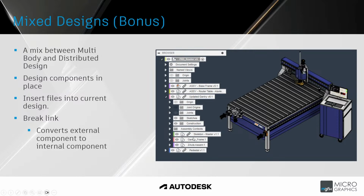One thing you can do is, let's say the updated gantry, we want to for some reason break the link to that external file. That is possible as well. This allows you to essentially insert a component. Let's say I'm going to use the pedestal actually as an example. It allows you to insert a pedestal. It might be a standard component that is used across multiple machines. You can insert that, but then break the link to the pedestal to then modify it and customize it for this specific machine.